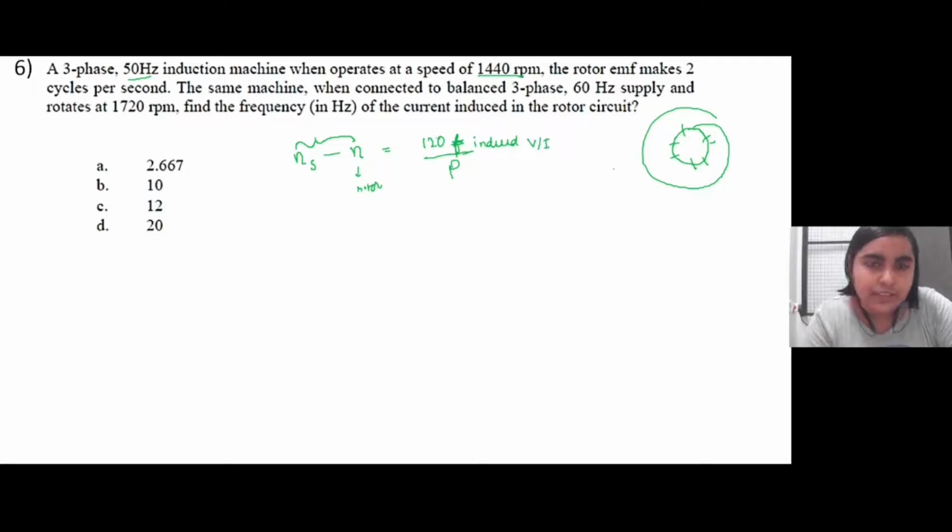The frequency of this is in relation with the difference in speed of the rotor and the stator. Sir has explained this in his lecture once. If you can recall, the frequency of the induced EMF or voltage, suppose it is f, is given as Ns minus the rotor speed. Do you remember this? Yes.